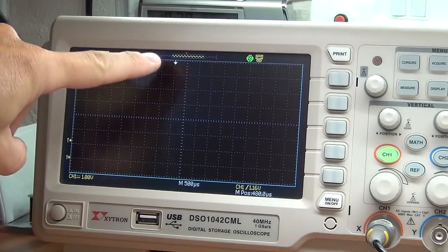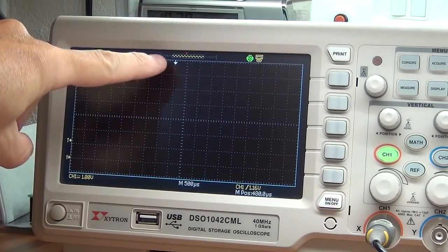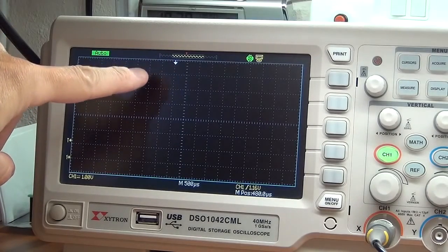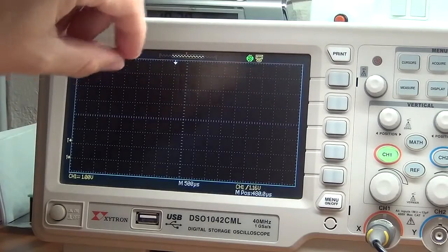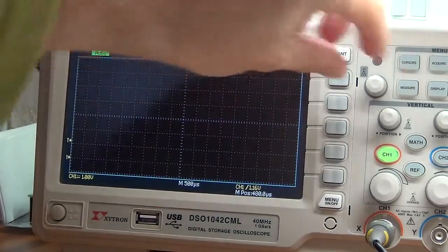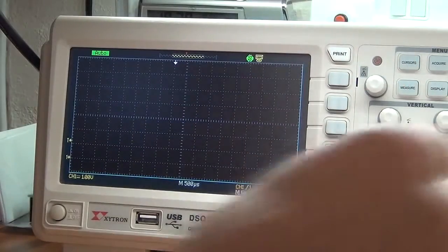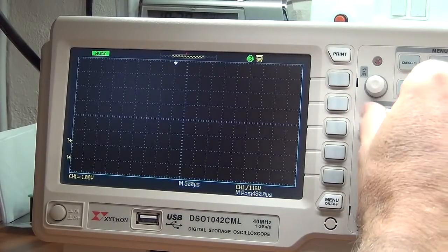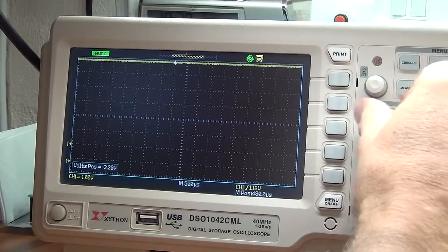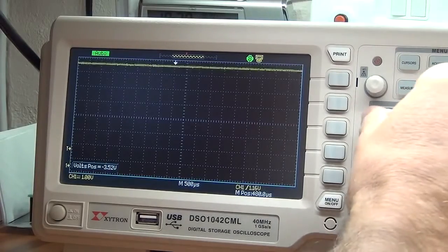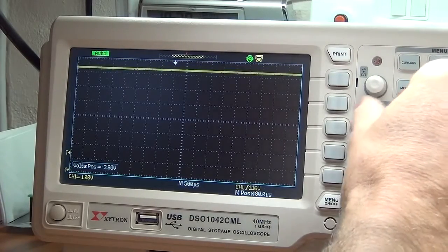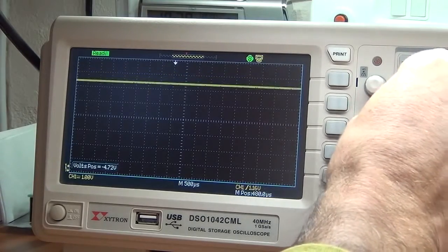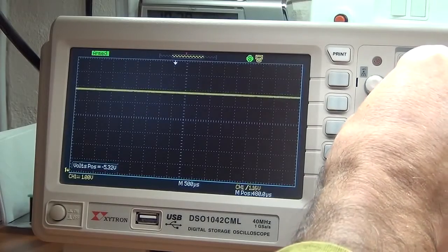And there's a little indication of that on my oscilloscope. You've got this little arrow which points out that the signal might be sitting higher up. So this leads into two things: me showing you what that signal looks like, and then using the buttons or knobs to bring signals into view. What I'm doing now is using the vertical position button, which we'll discuss shortly, to bring that signal down so that we can have a look at it.